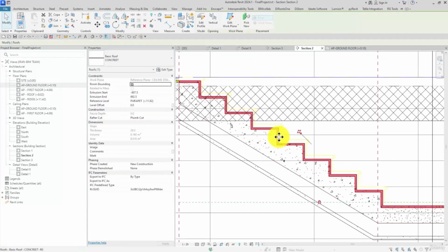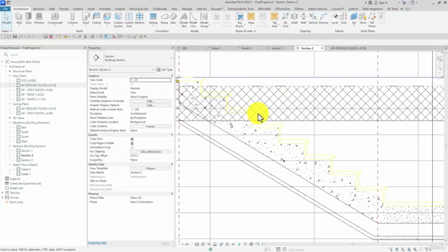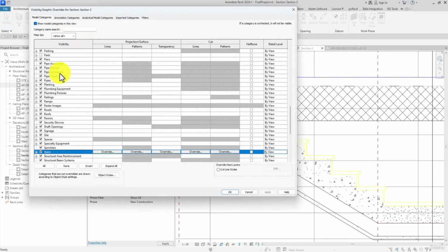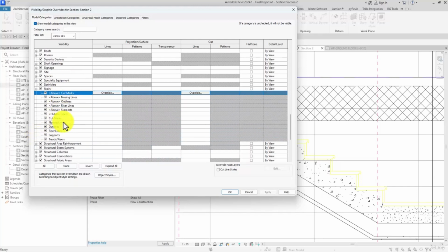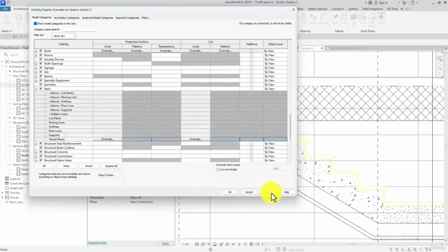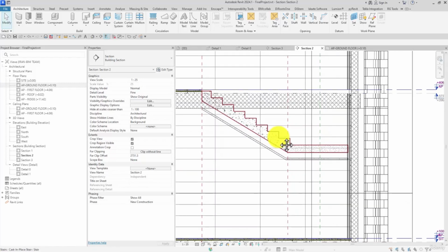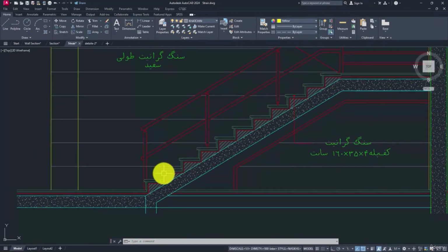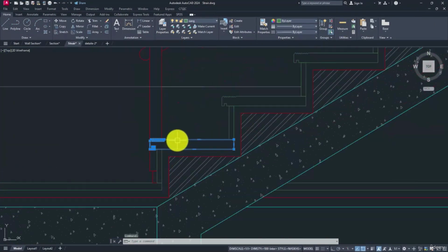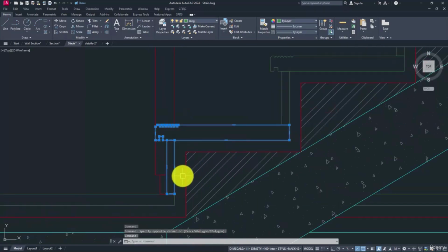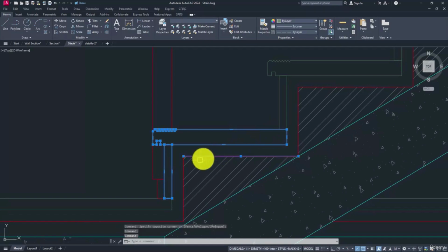Let me see, I align these parts since it was skipped. Finish. Anyway, firstly I have to open the hide in view element. I select these stairs options or the subcategories, and then I hide them since we only want the structural part or elements. After hiding the treads and other items, we want to model them as detail items. If we model one of them, then we can make some duplications or array them. No, they are all the same.